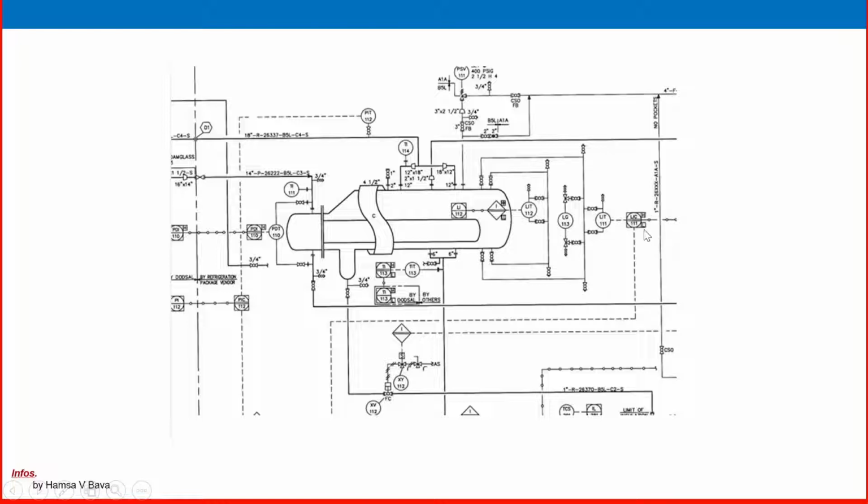See, on the right side of the PLC controller it is written low and high. So the PLC controller is programmed to show an alarm on high liquid inside or low liquid inside, for protection of the tubes against thermal damage.